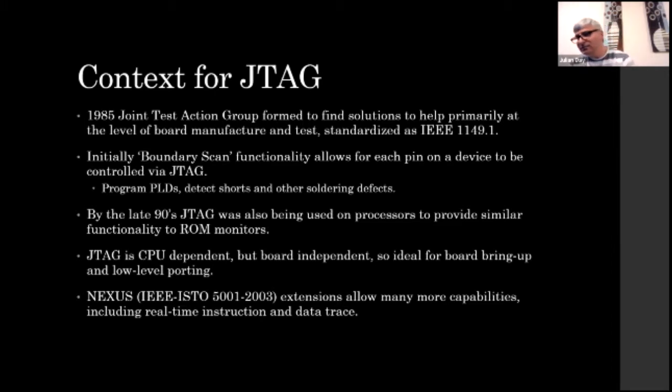As a standard, JTAG was designed not to be CPU dependent, but it's really pretty much for any relatively complex chip that you have on the board. Some Ethernet PHYs have JTAG support. Often you'll see it on bus controllers, again, things like VME or compact PCI bridges and so on.